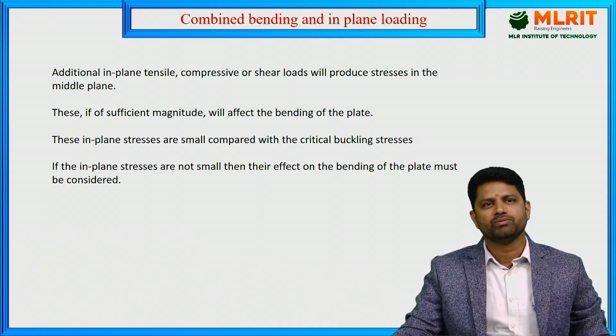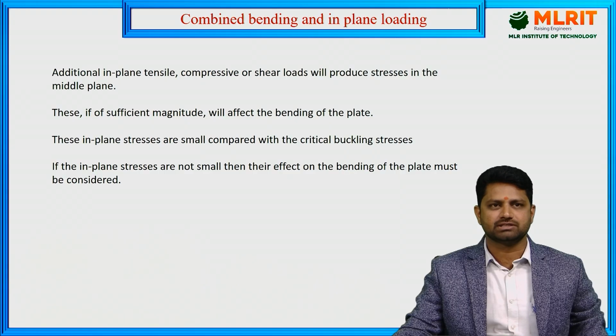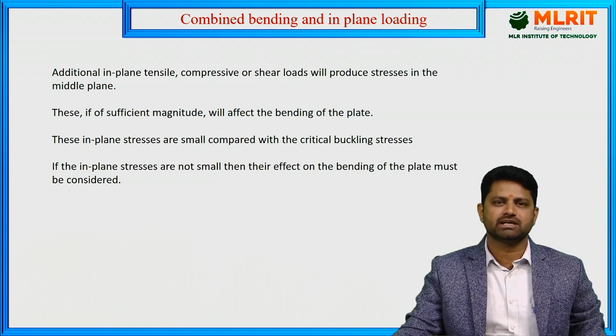These in-plane stresses are very small when compared with the critical buckling stresses; if they are not small, then they are going to affect the bending of the plate. Therefore these in-plane loads must be considered in the analysis of thin plates subjected to loads.